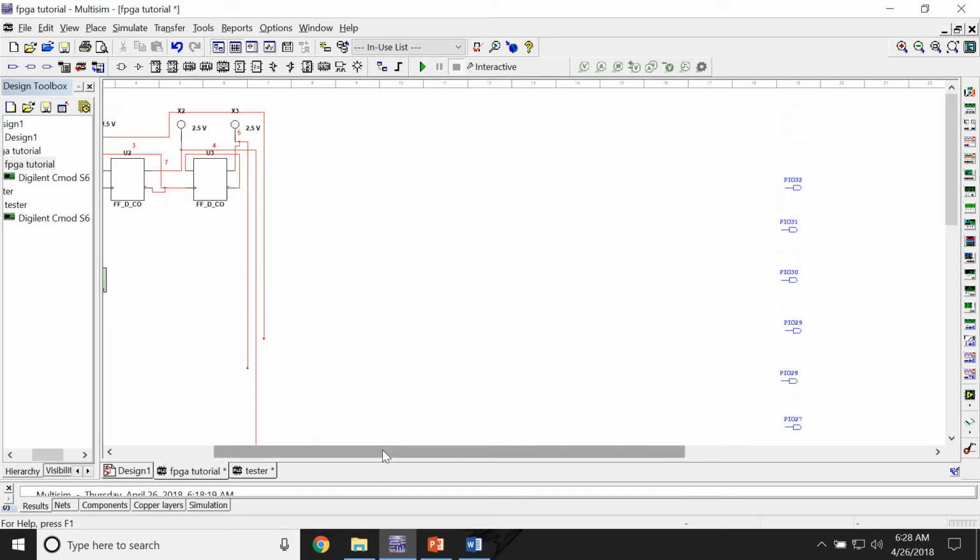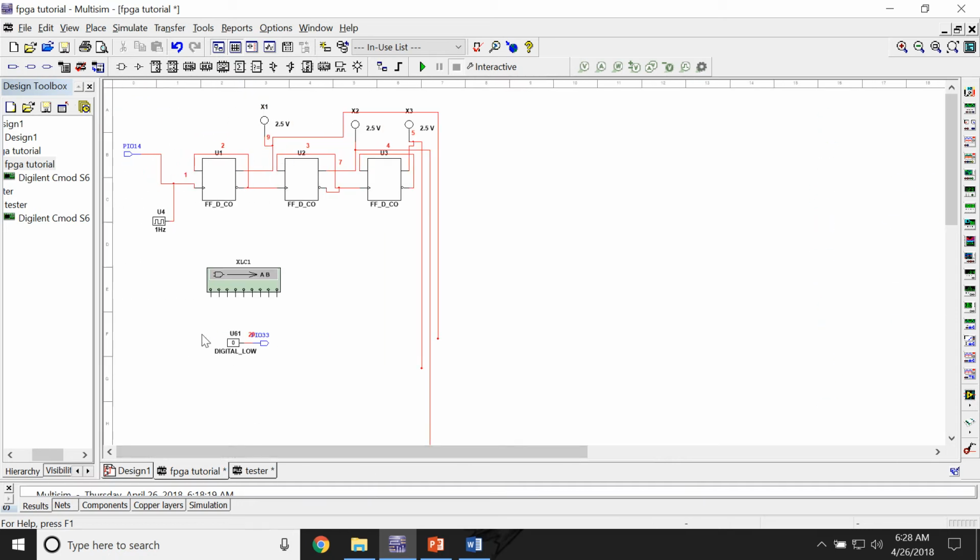There is also this little thing right here, PIO 33. If you're building this, it only makes it so that it only turns on one of the 2 7-segment displays. That's what this does. It doesn't matter whether it's there or not. It would just light up both of them. Then you need to make this.